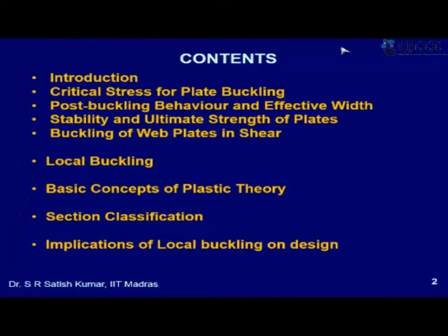Along the way, I will also be touching upon some basic concepts of plastic analysis or plastic theory, which is very useful to analyze and design many types of structures. And we will see, because we are going to limit state design. Yesterday I told you that plastic analysis is one of the enabling features which helps us to go beyond the first yield point, and then it tells us exactly at what load a particular beam or a structure will collapse. Okay, and then we'll use section classification and how local buckling helps us in the design.